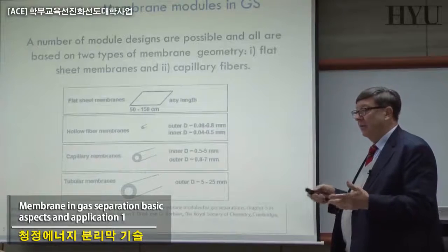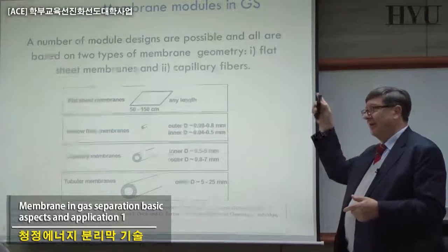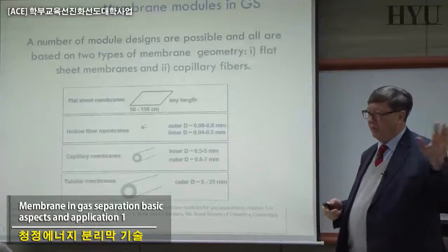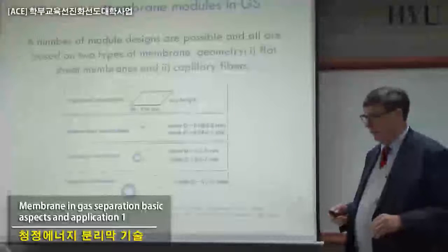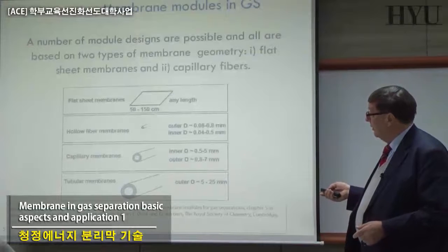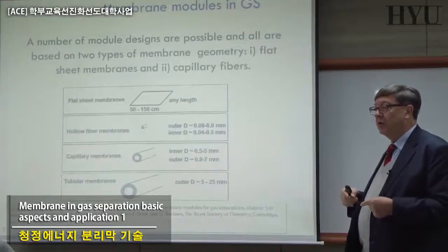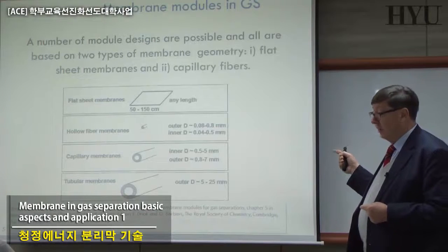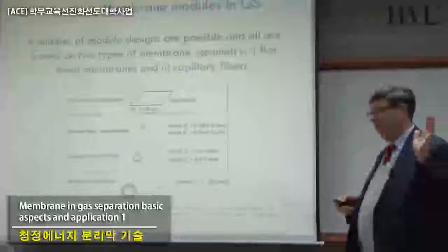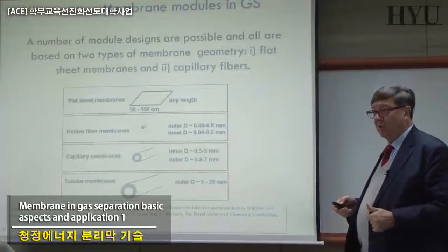In air, the prevalent components are nitrogen and oxygen. They are 80%, 20%. The other ones are 1%, 0.1%, etc. A very different situation from what you can sometimes have in the liquid phase. So people were assuming, and they were right, that hollow fiber is the most interesting configuration for gas separation, because you basically don't have a problem of plugging entering the module, which was the problem in reverse osmosis.